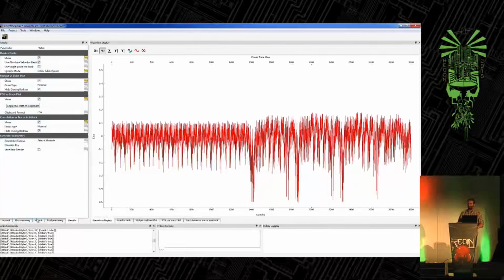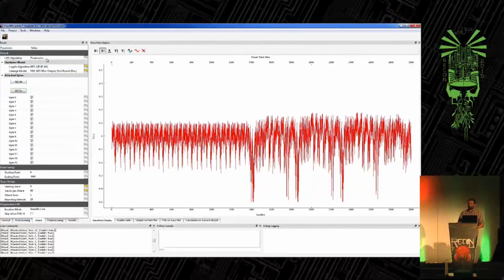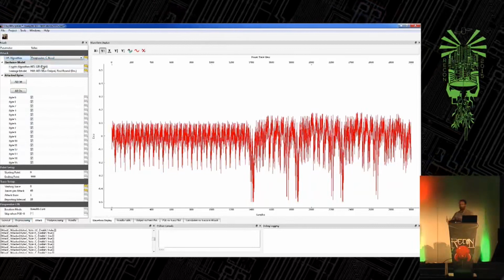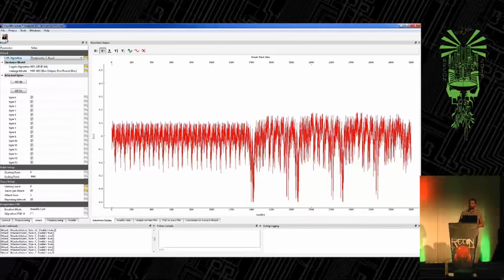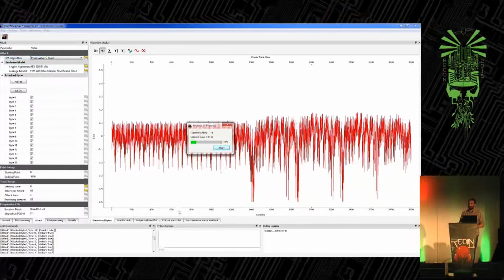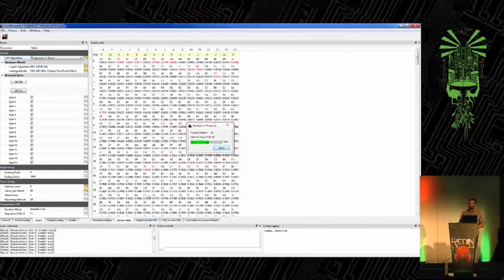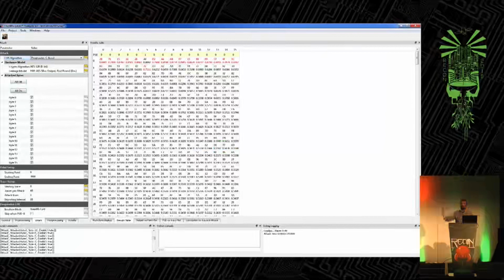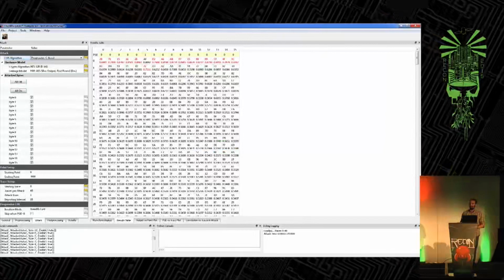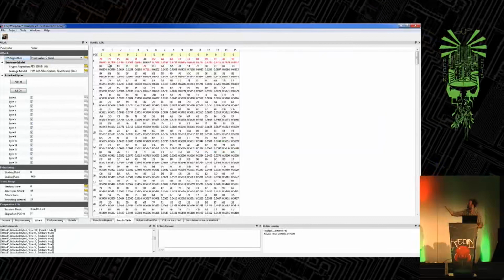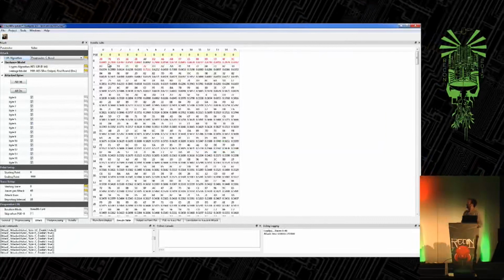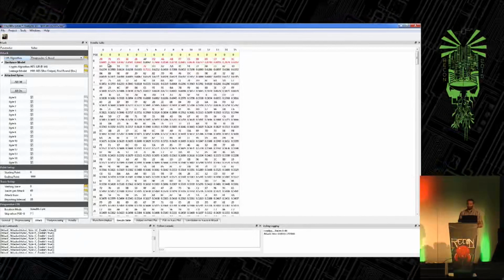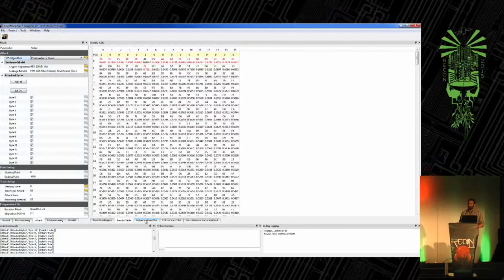That was the waveform I just captured. For the attack, we have to know a little bit about the device. In this case, I know it's AES-128, and because it's on a microcontroller, there are certain power models we use. I talked about that in previous presentations, so I'll skip that. The analysis is running, and the key in red is the correct encryption key. It knows the correct key because I've told it what it is. You can see in this example, in 50 traces, it almost entirely recovered the key. There's one byte that maybe needed a few more traces. But it's very, very fast. That was a few minutes start to finish for the whole demo.